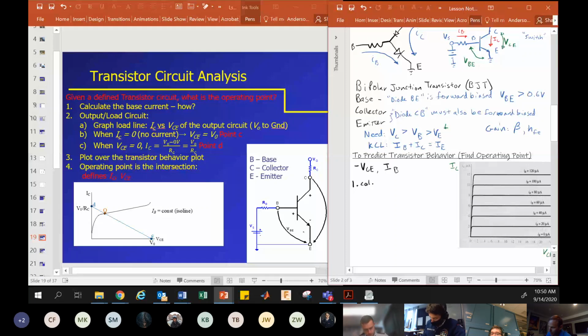How do we calculate current in this class? Ohm's law. Ooh, close. It's that three-letter acronym I like to foot stomp a lot. KVL. KVL, let's do KVL. Okay, and you're thinking now, what is he even talking about? If we look at this, here's the base. This forms a circuit from this source through this resistor through the transistor to ground.